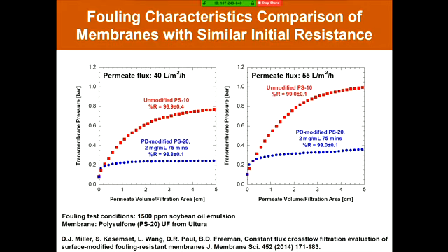We have been studying the use of these kinds of membranes for flowback water purification. And so when oil and gas wells are hydraulically fractured, one pumps a lot of water underground, and about 20 to 30% of that water comes back. You can use well over 1 million gallons of water per well, and you get 20 to 30% of that back in the first few days of production, and that water is dirty.